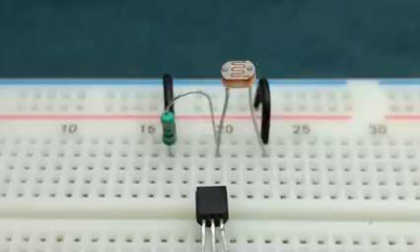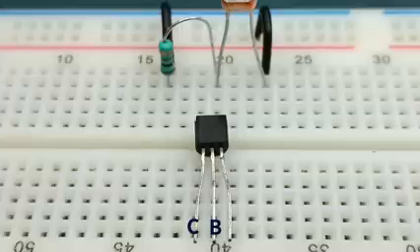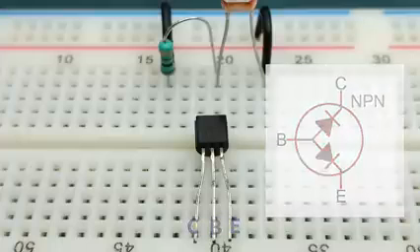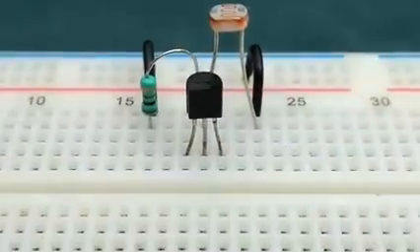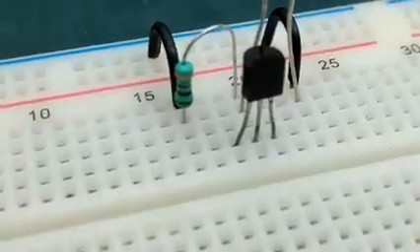using a transistor. I'll be using an NPN transistor BC547. If you intend to use any other NPN transistor, check the pin configuration from its datasheet. Now, for an NPN transistor, the base is of P junction, and more positive bias or voltage at the base will turn on the transistor. So, connect base of the transistor, which is at pin 2, to common point between LDR and resistor.